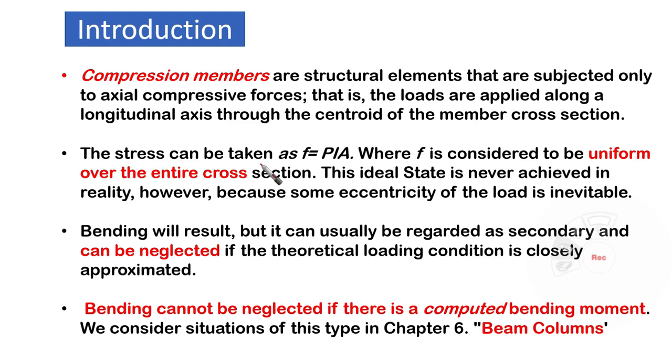The stress can be taken as P over A, meaning the compressive force over the area of the cross-section, where f is considered to be uniform over the entire cross-section. So we are considering that the whole cross-section is uniformly stressed in compression.